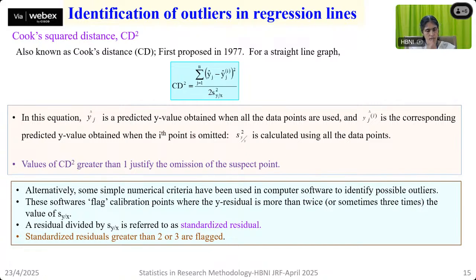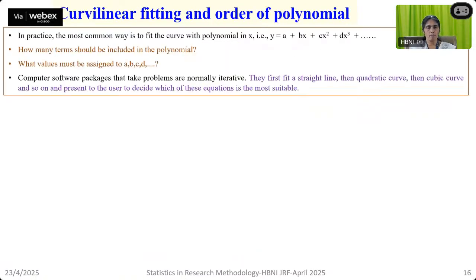An alternate way of evaluation is by flagging. While flagging, we do the standardization of the residual by dividing each of these values by the total number of measured data. Then if the standardized residuals come out to be more than 2, or sometimes the relaxation is there up to 3, then we flag, meaning omit it as an outlier and go ahead. Flagging is like exclusion only.